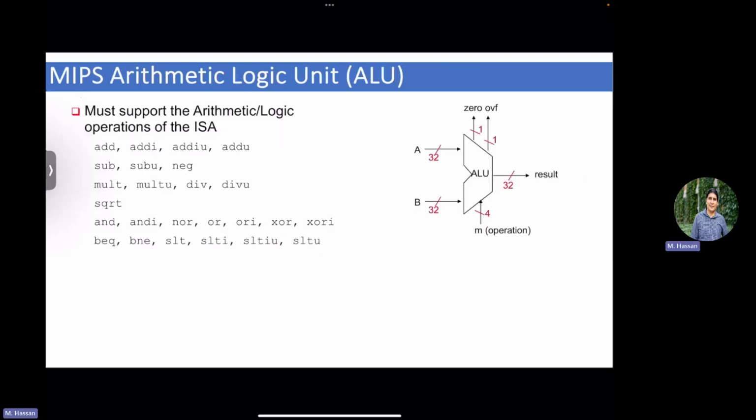Yeah, this is something that will come into play in our circuitry. We already have seen it in the offset of the branch. If you have a small number that you want to add to a larger number, like our offset was 16-bit, and I'm adding it to a 32-bit program counter, but your adder is regular, it's 32 by 32, so how do you extend the 16-bit to be 32?